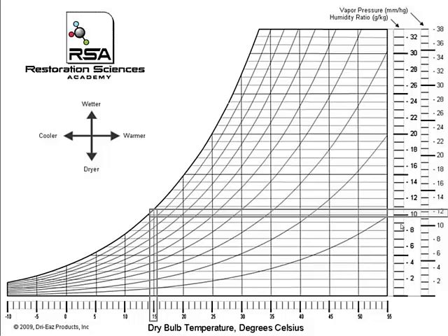In order for that water vapor to move from one location to another, whether it's from one room to the next, from the outdoor environment to the indoor, or even from a building material into the surrounding air, better known as drying, there has to be a difference in that vapor pressure and that around it. And when we look at a psychrometric chart, we can evaluate these different conditions in these different places.